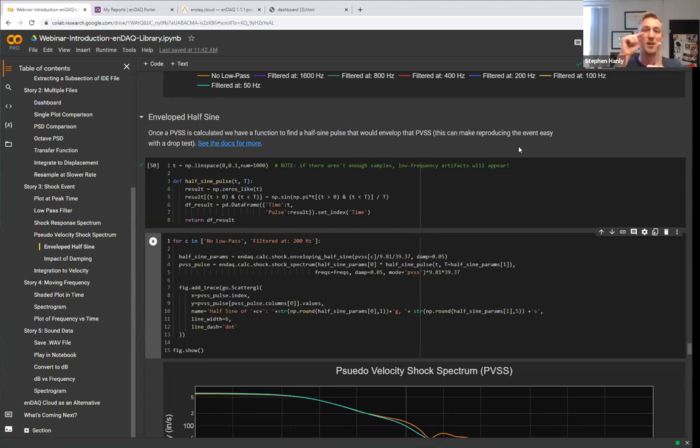It's impacted by just where you get the event. You could have the same sample rate, the same event, and get two completely different peak acceleration levels just based upon how the samples lined up with the actual shock. It's going to lead to more confusion and conclusions that may be misleading. I really strongly encourage people not to do that.